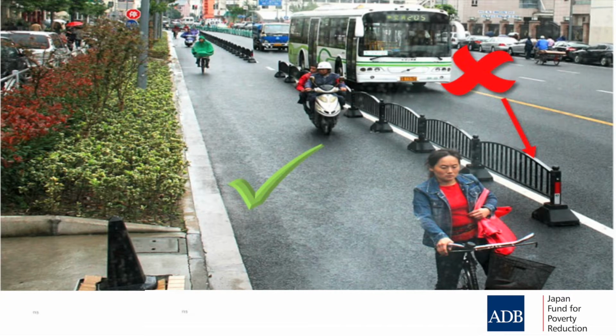Now, if you are going to have dedicated lanes that mix bicycle riders and motorcycles, it's important to start thinking about the speed differential, so the difference in speeds. In the notes, I've recommended that you try to limit the speed of motorcyclists if they're going to be mixing with push bikes, and try to get that speed differential closer. It's a hard thing to do. You may need speed limits, you may need enforcement,